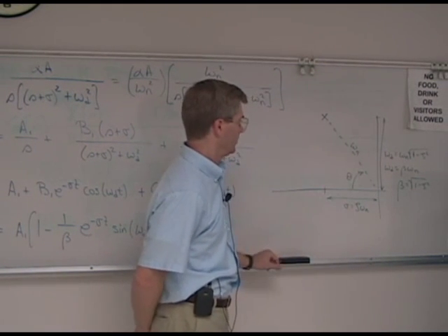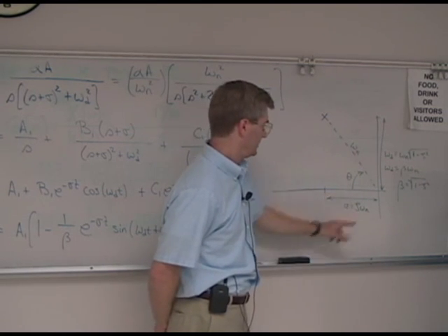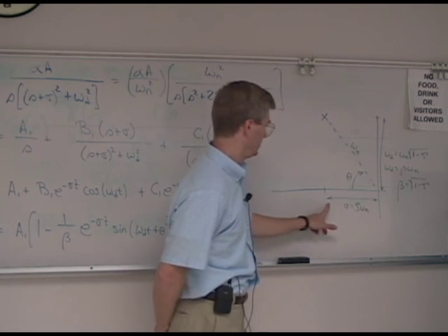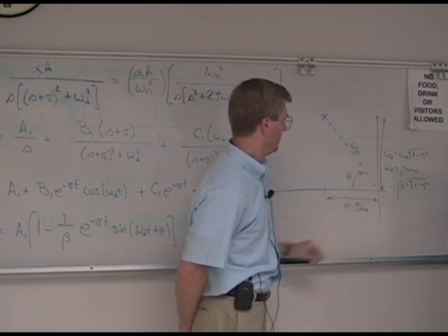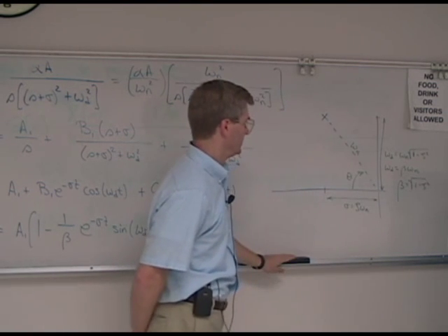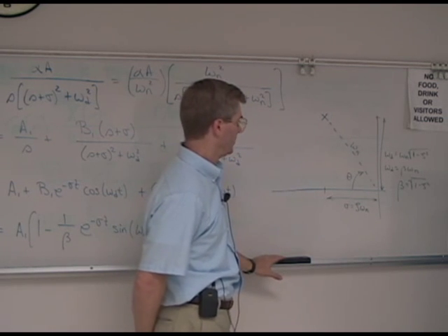in our s-domain plot. That's related to the angle theta, or that's the zeta value is related to theta. And this is our damping, sigma, and this is our imaginary part, omega sub d, with the radial distance being our natural frequency associated with that complex pole.